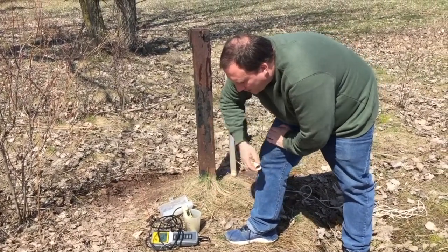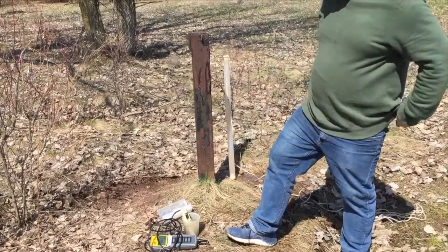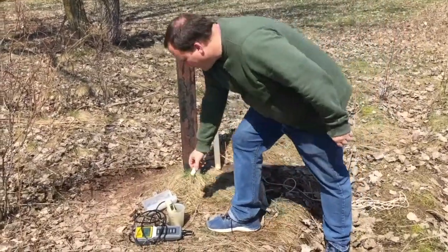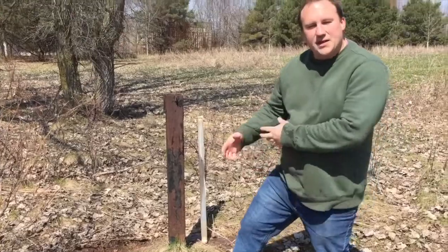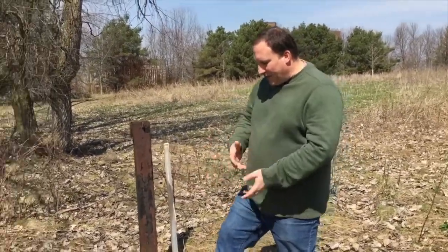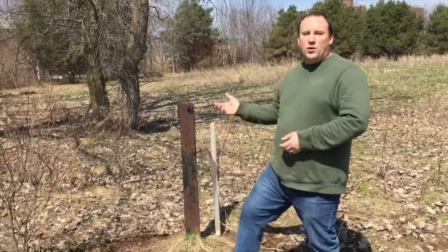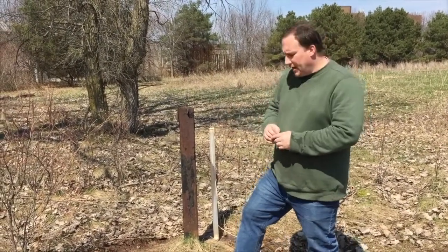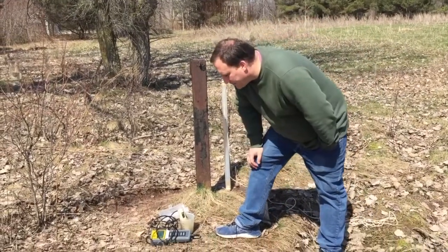The temperature of the water is 9.8 Celsius. It's rising here in the sunlight and with the air contact, but it's 9.9 now. It'll be 10 shortly. It's 10 already. So usually what I do is get this thing wetted, let everything come to something close to a stabilization, and then I do one more bale, put it in there so that you're getting a fresh temperature and fresh conductivity value. It's a little bit more accurate that way.